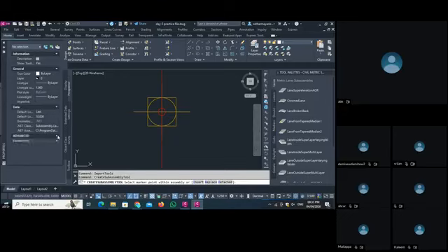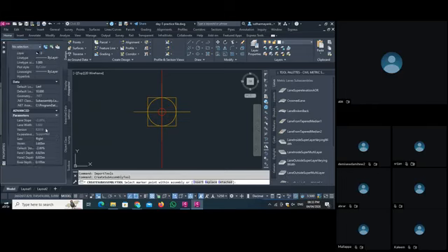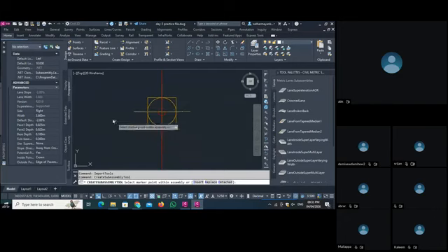See, in the advanced option, you see all the parameters. Then what is the side? Right side. So if I place it here, it will show the left side. If it is not shown as left side, then you have to make it a left side. Then the width of the road, then the slope of the road. Then it has 1, 2, 3, and 4 layers, and the thickness of all those layers is provided here. Super elevation, there is no super elevation provided. So you can change all these things from here. If I want the width as 3 meters, you can type 3 and enter.